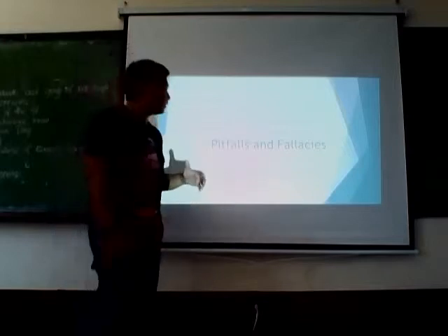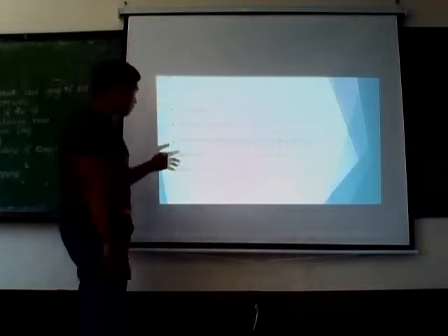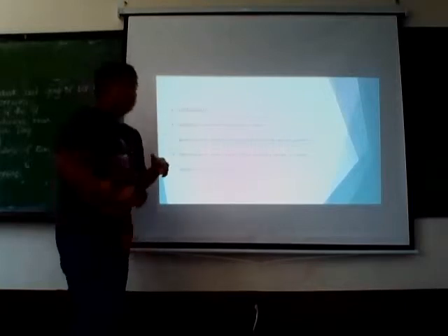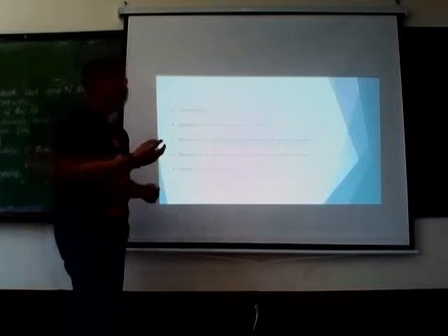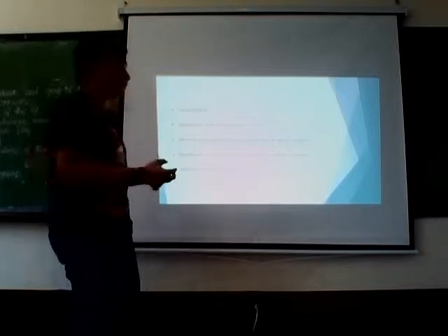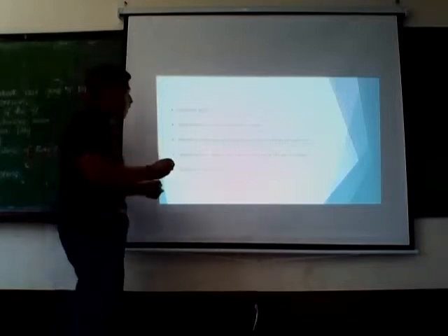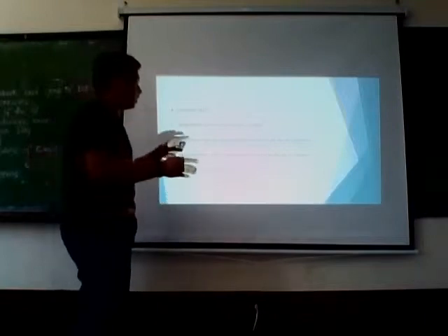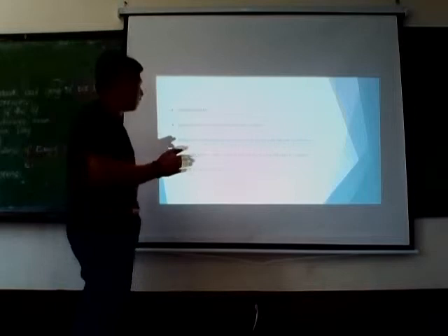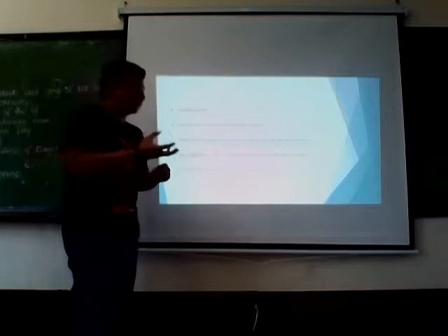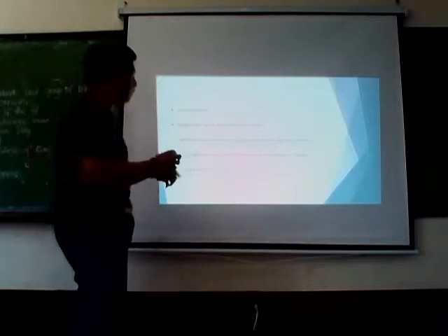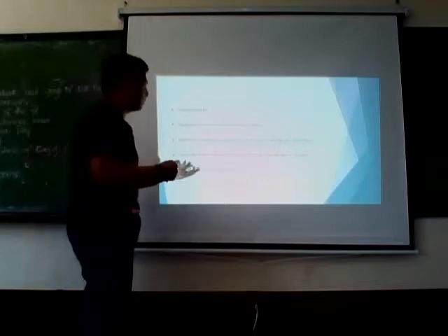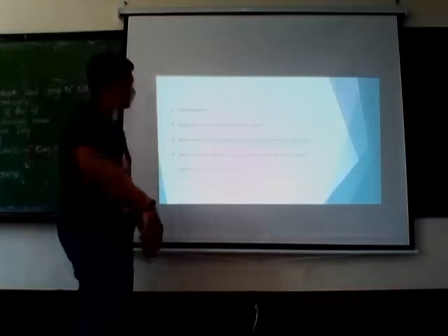Pitfalls and policy. Now, there are different types. Oversizing gates. They said that oversizing gates increases the power consumption, but it does not. Designing for speed without regard to power is a lot better than not designing for speed, but it takes more energy. Other pitfalls: reporting power at a given frequency instead of energy per operation, reporting power delay product when energy delay product is needed, and failing to account for leakage.